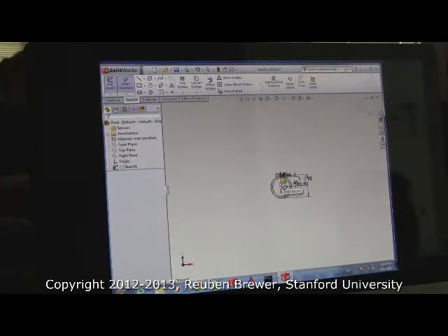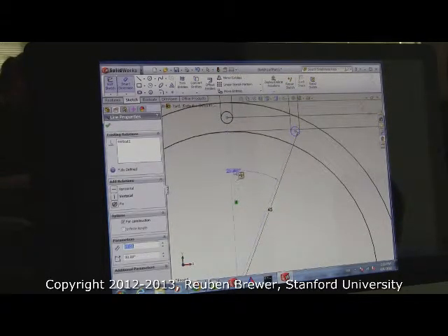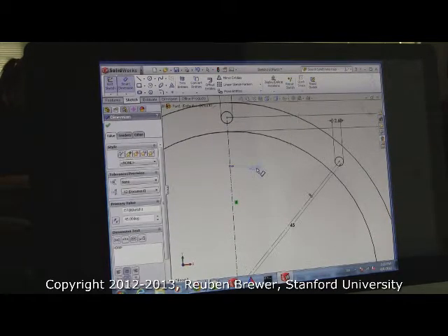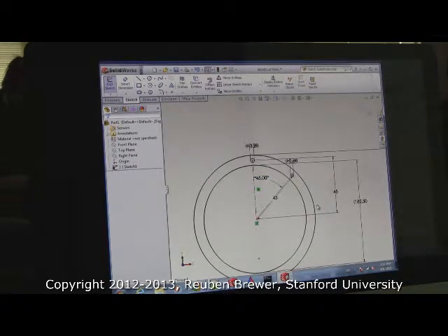Basically, SolidWorks thinks you want to click on whatever is nearest to your mouse cursor. If you're zoomed way out, so that your image is super small, it doesn't have sufficient resolution to select the proper thing. So it will keep selecting the wrong thing and your sketch will get screwed up. There's no reason to work with small. Always zoom way in whenever you can. So let's select those two lines, angle in between, 45. So the two common mistakes we've learned are Escape and to zoom in. You don't want to work too zoomed out. For one thing, it'll strain your eyes.